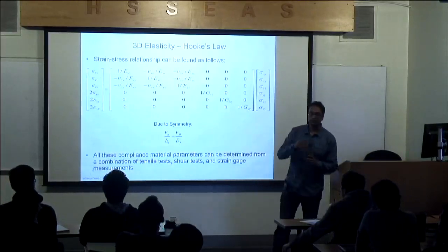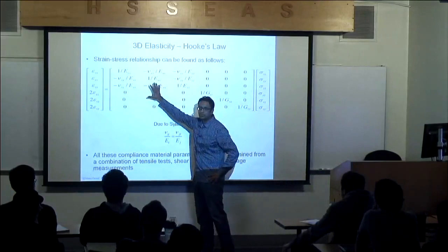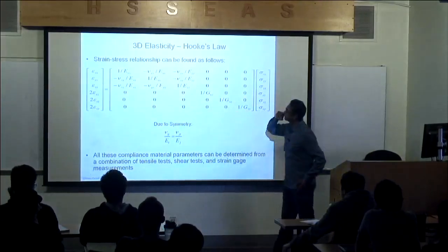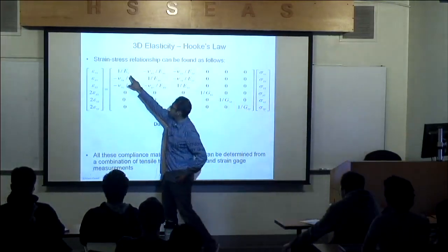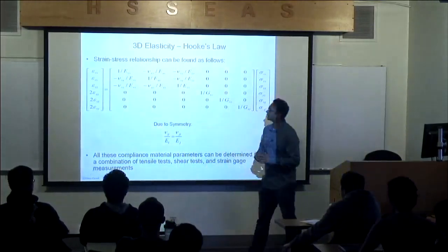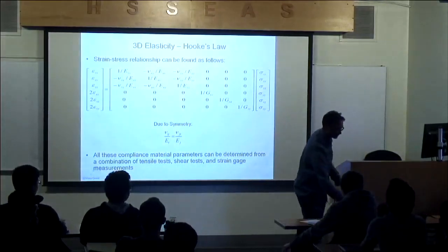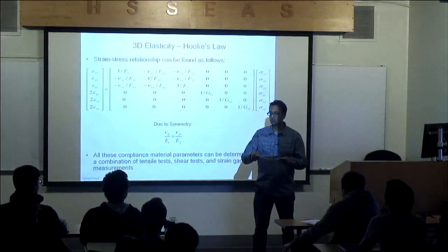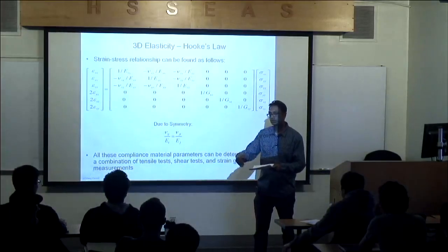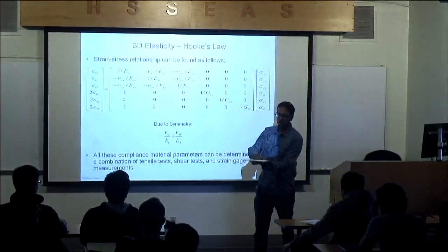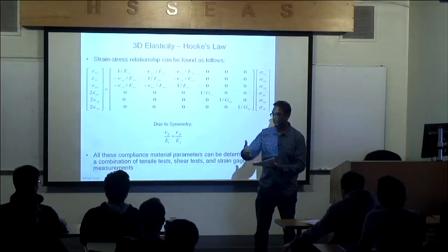For a composite material, which I already covered in lecture number 4, please review that again. You have several engineering constants that define the constitutive matrix, how the strain relates to the stresses. And we covered that these materials have directionality. For example, EXX and EYY are the in-plane directions of the composite. If I have a lamina, EXX will be along the fiber direction. EYY is transverse to the fiber direction, so in this direction instead. EZZ will be the transverse direction, so the modulus measured this way across a ply. So if you have a bunch of plies stacked up, basically that direction.